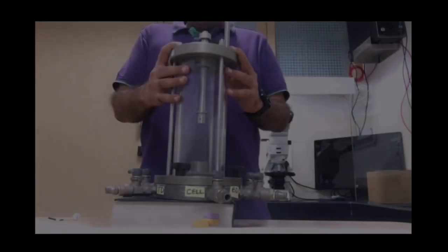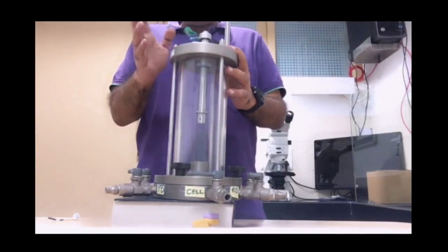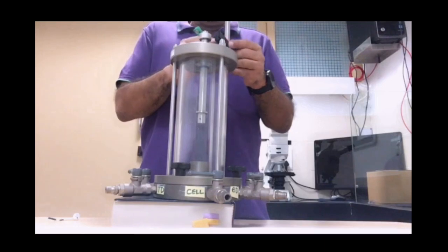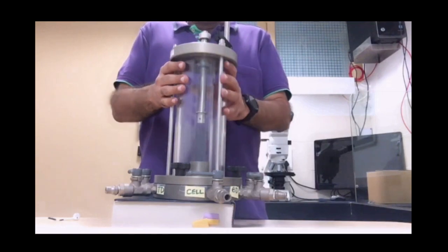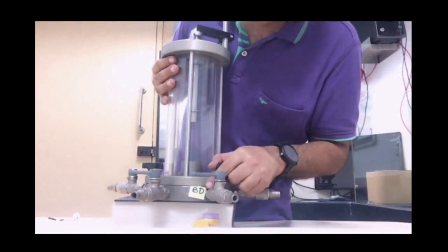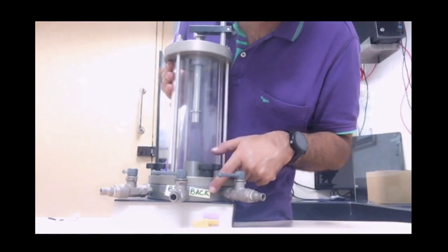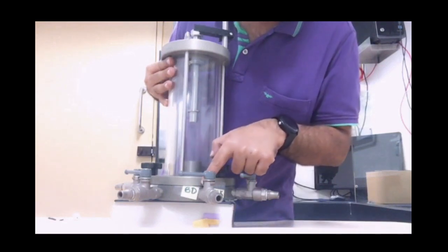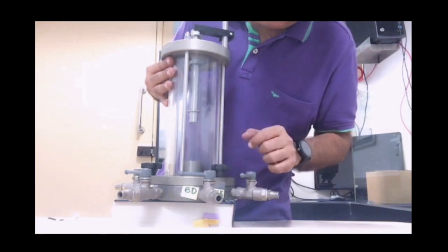The second procedure for saturating the sample is by using back pressure. So we have just seen back pressure in terms of the quantity, but let's physically look at how you apply back pressure on a triaxial cell like this over here. For back pressure, the bottom drainage which we had, the same valve I'm going to use for back pressure. So I've written back over here. Now you've got an extra label which says back. So the same valve is now bottom drainage, and back pressure is the same valve.